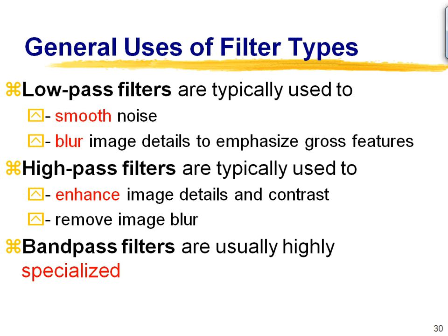Now band pass filters are generally very specialized filters, and generic band pass filters are not something that are pre-designed and used. They tend to be very application specific, because in order to design a band pass filter, which means we want to retain some middle range of frequencies, we need to know what that mid range is. It's very difficult to design a generic filter without understanding what frequencies we want to retain. Okay? So band pass filters tend to be very specialized.